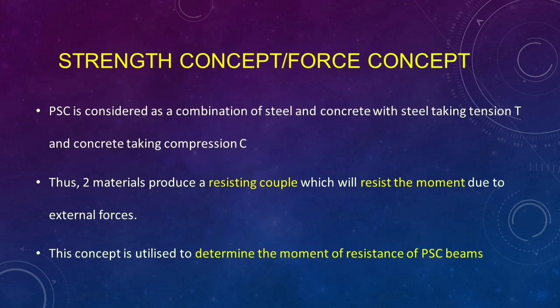Moving on to the second concept, strength concept or force concept. In RCC, steel reinforcement takes up the tension and concrete above the neutral axis takes up the compression. A couple is formed due to the resultant compressive force C and tensile force T, so that C is equal to T. This internally formed couple resists the moment due to external forces.